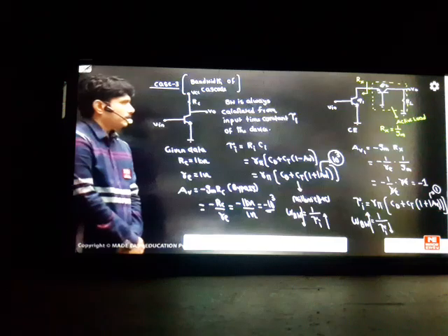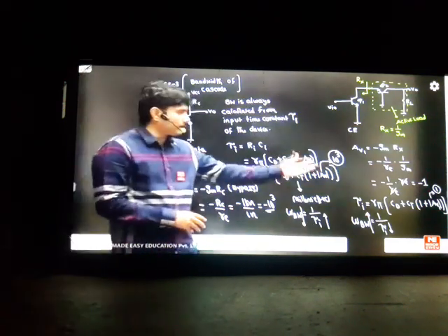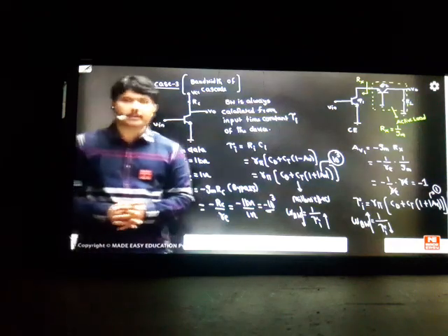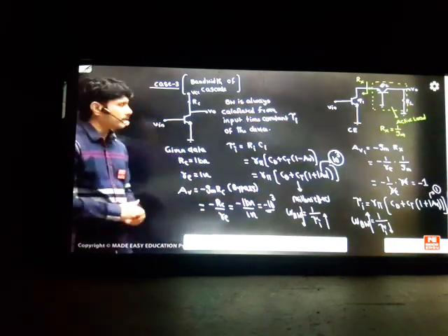So that is the main purpose of using this special topic in our electronics. This is my background scientific analysis to teach the students why this one is enjoying more bandwidth and why that one is not enjoying more bandwidth. A common emitter has a larger time constant, a common cascode has a smaller time constant because of these issues. With this I have covered this concept successfully.